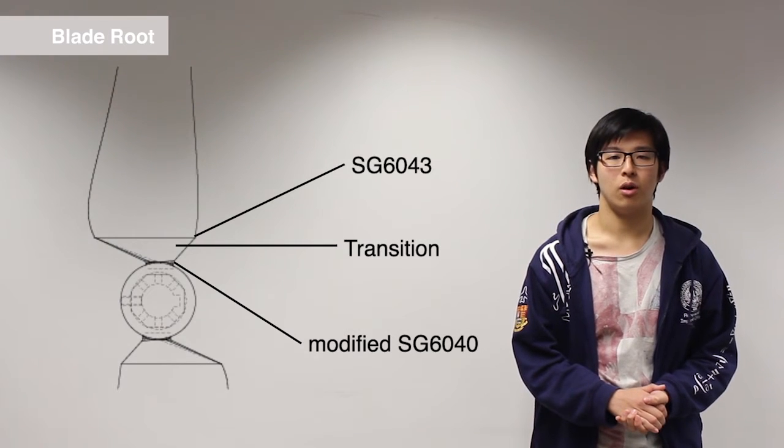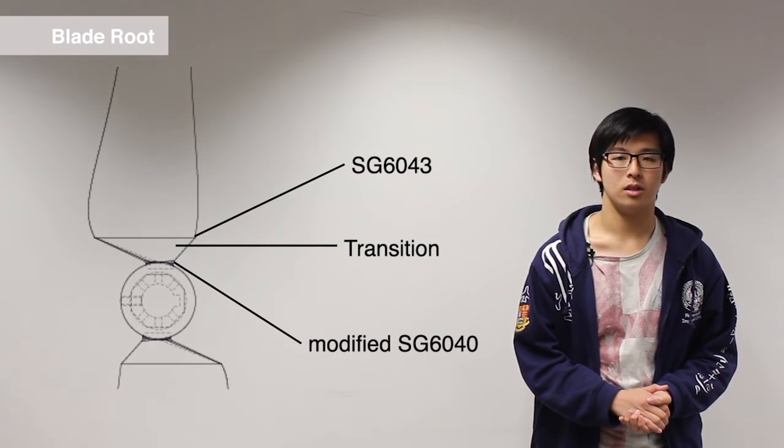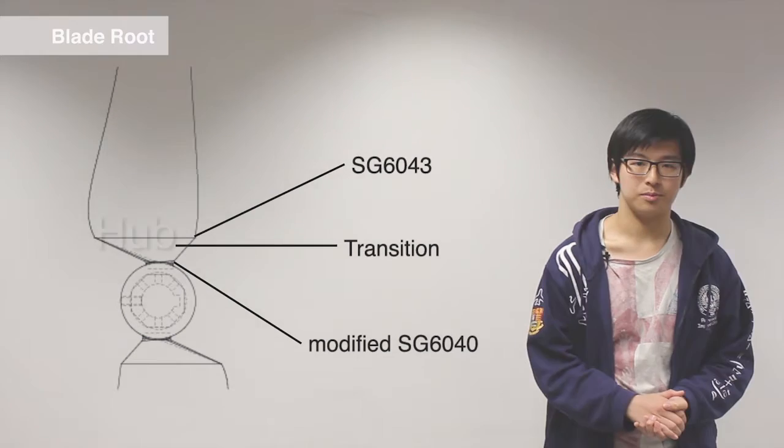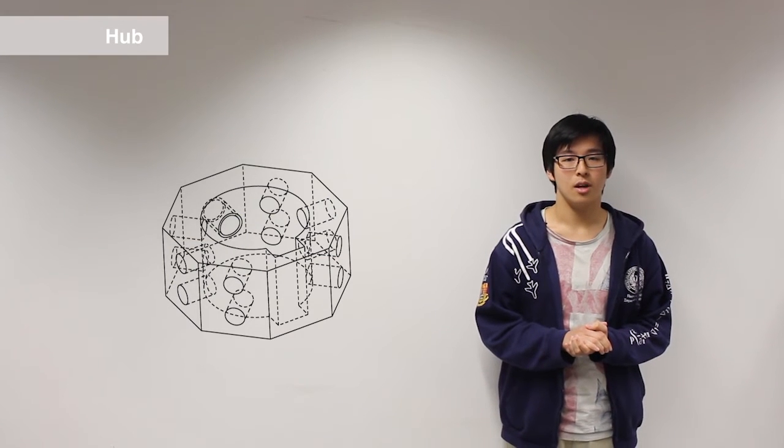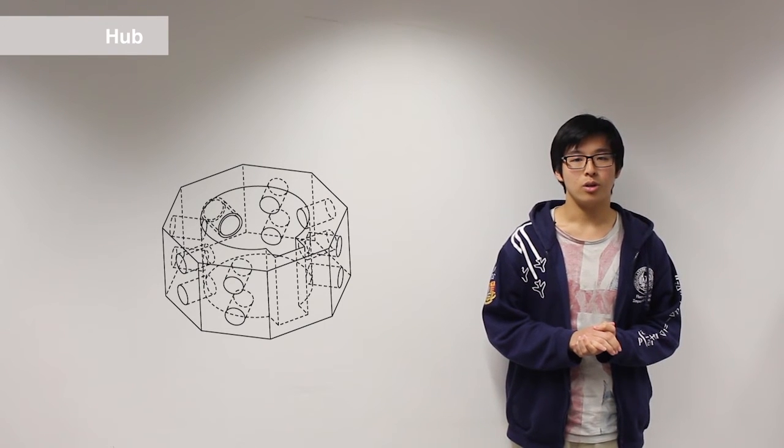Thirdly, by choosing an airfoil of the same family as SG6043, the transition from the root section to the blade is smoother. The octagonal hub was designed in order to relieve the stress intensity while maintaining the grip between the hub and the cone. We also drilled holes to reduce the mass to just over 9 grams.